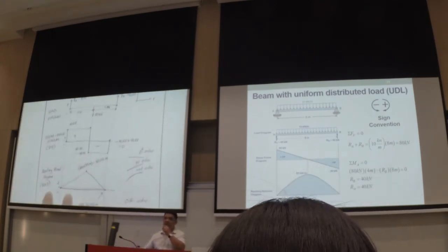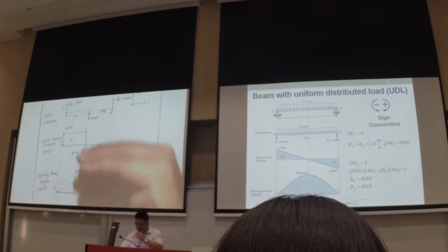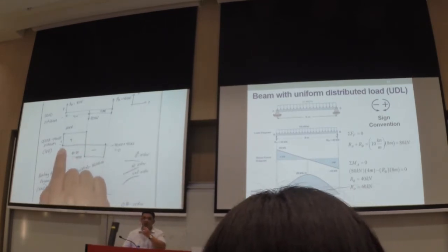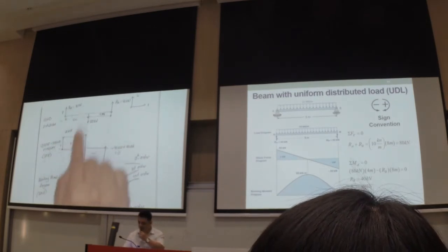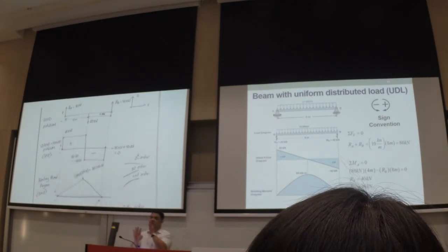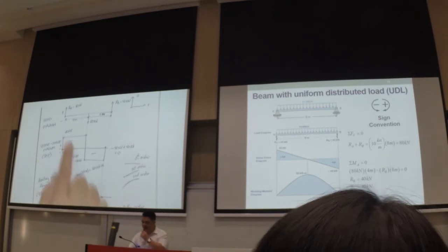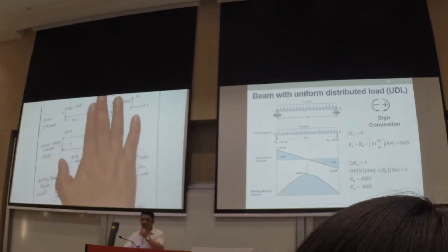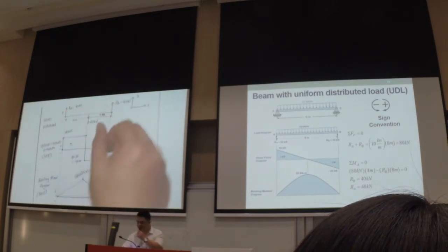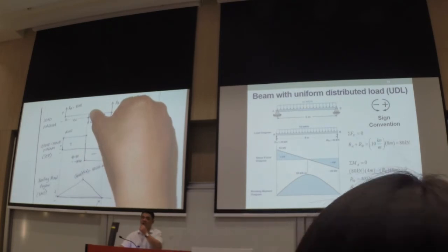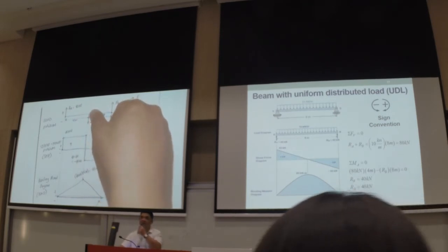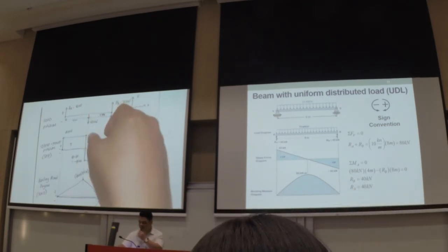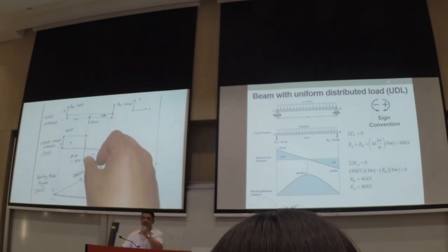So settle down now. Let me just explain this one. We're moving from left to right. The reason why we go up is this one goes up. And we go constant here because there is no disturbance, so we just move along. Meaning that the effect of that force, 40 kilonewtons, will be constant along the beam until it reaches that point. Then it becomes a different value, meaning that this one from here to here goes down. And that's the magnitude.